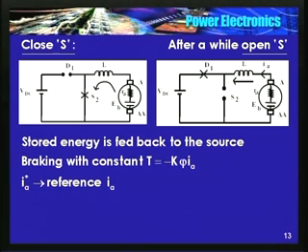Eb is decreasing, assuming VDC is constant, the difference between these two voltages appears across L. This is falling, this is held constant, therefore voltage across the inductor is increasing. As the speed falls, Eb falls, therefore the difference between Eb and VDC increases.